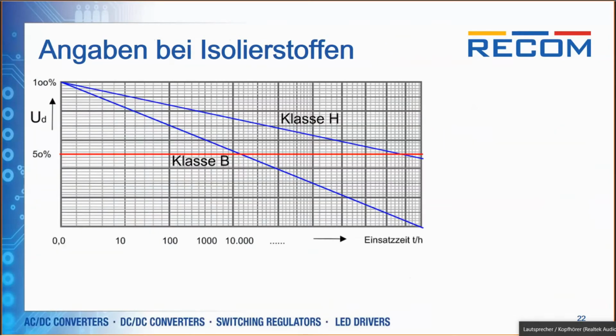I wrote it in German, okay. So you can see differences in insulation classes when you use class B or class H for the same conditions. You can see class H will survive the stress much longer.